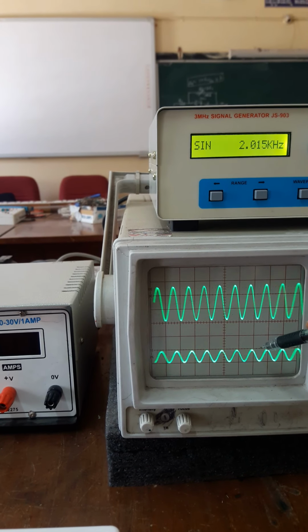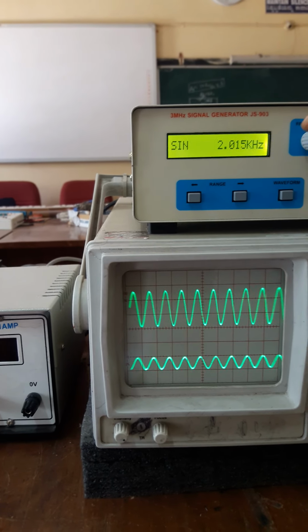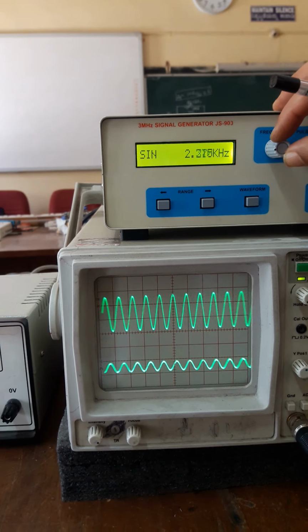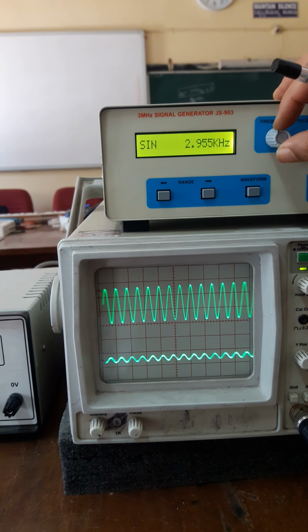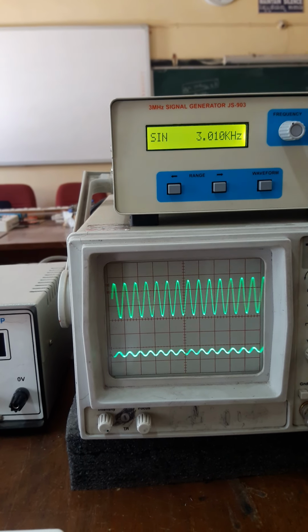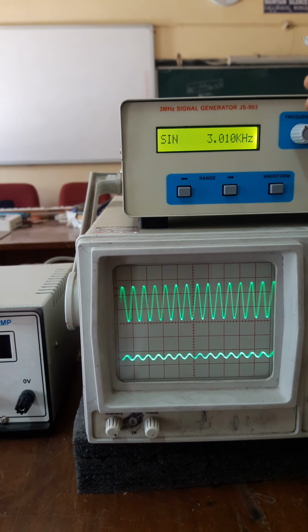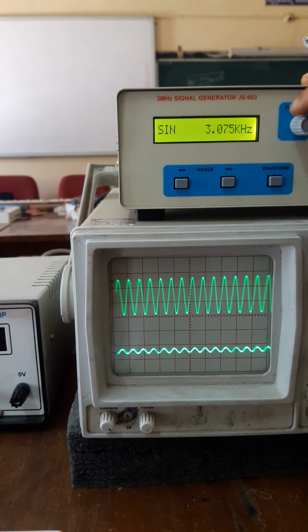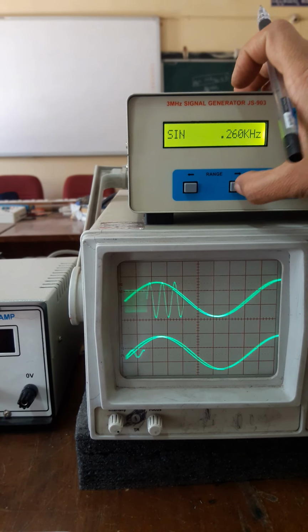So the output voltage is decreasing. Further, if I increase it to 3 kilohertz and keep going on increasing the frequency, you can continuously observe the output voltage. Again the output voltage is decreasing. Further, our design is for 4 kilohertz. So if I set that 4 kilohertz frequency,